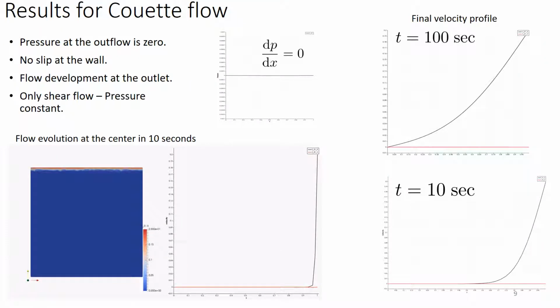And once we implement the Poiseuille flow, we verify the tool. We also implement this in our problem, which is a Couette flow, where we first have no pressure gradient across X, and this is the corresponding flow where the bottom plate is stationary and the top plate is moving with a specified velocity, which gives a shear flow or tangential flow.